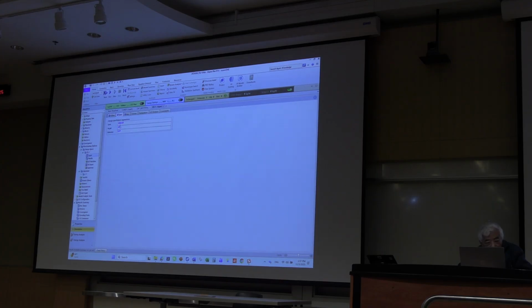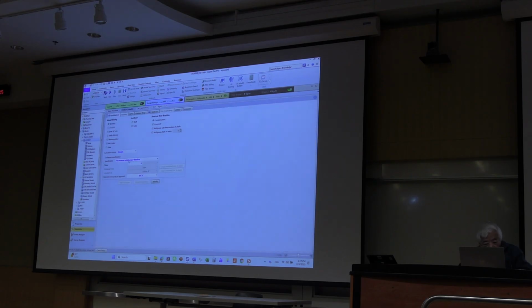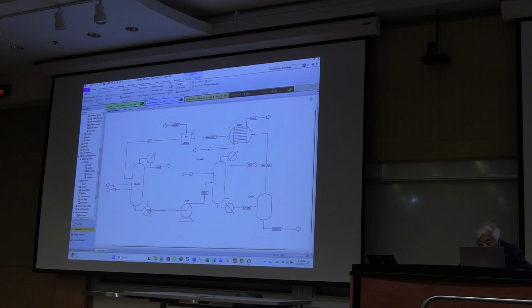You specify this to be 45 degrees. And how do you determine how much inlet mass flow rate instead of 50? What should be the number to get this 45 degrees and also fully condense the vapor? That is this design spec. Vary mass flow, cooling water coming in, CW1. Then use a mixer. Recycle